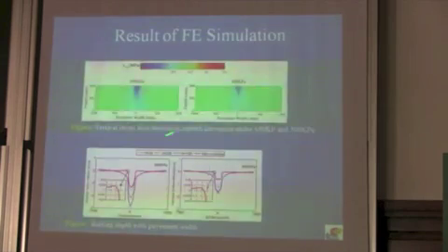Okay. All right, so I think the first view graph is not so important. I think this last one, the second one, is more important. So at 2 different loading levels, this may represent a small car, like maybe I'm driving, or a large Mercedes that Samuel may be driving, would be this one, right? Okay, all right. So after 1,000 seconds, which is about 4 hours, you can generate 2 millimeters of permanent deformation in the pavement.